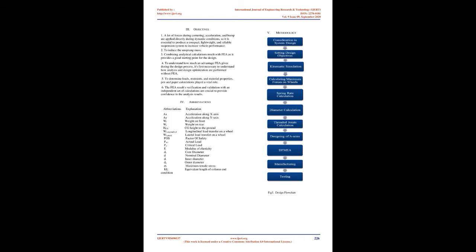Introduction. The FS car's suspension controls the angle, position, and velocity of each wheel to maintain a high value of mechanical grip while transmitting the forces generated by tires to the chassis. A reliable method to determine the forces produced by the road loads and suspension members was opted. In this paper, a detailed analytical calculation was explained for deciding the A-arm diameter using a set of calculations. The component is designed to be cost-effective, durable, and lightweight.